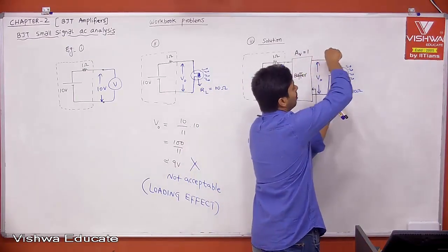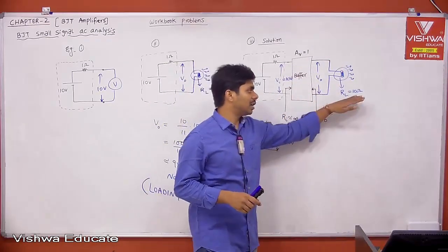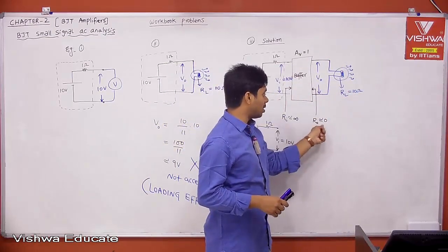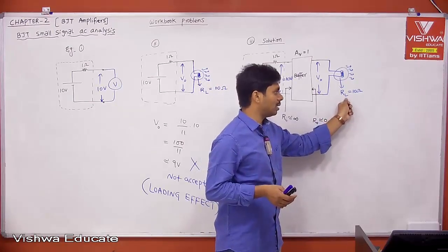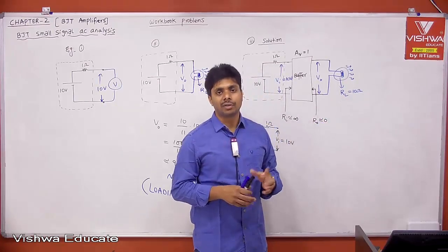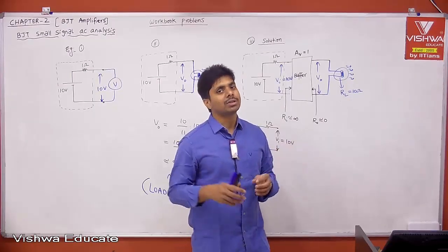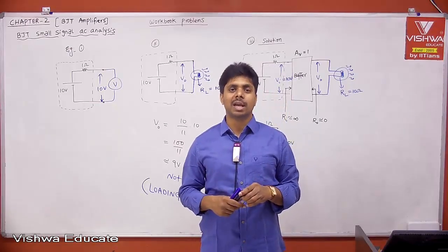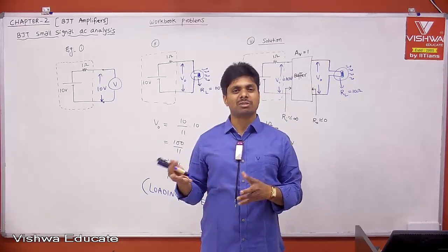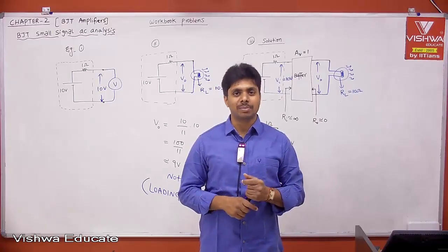the same voltage you can apply to your load, right? Maybe in this example, because I have taken 10 ohm, if you take R0 as 0, that is fine. But ideally, R0 should be very much less than RL. If you take an audio amplifier or actual circuits, in the case of the CC amplifier, the load is not 10 ohm, it is 10 kilo ohm, right? And the output impedance of your CC amplifier is 40 ohm. Then 40 ohm is very small with respect to 10K, so indirectly we have proper impedance matching.